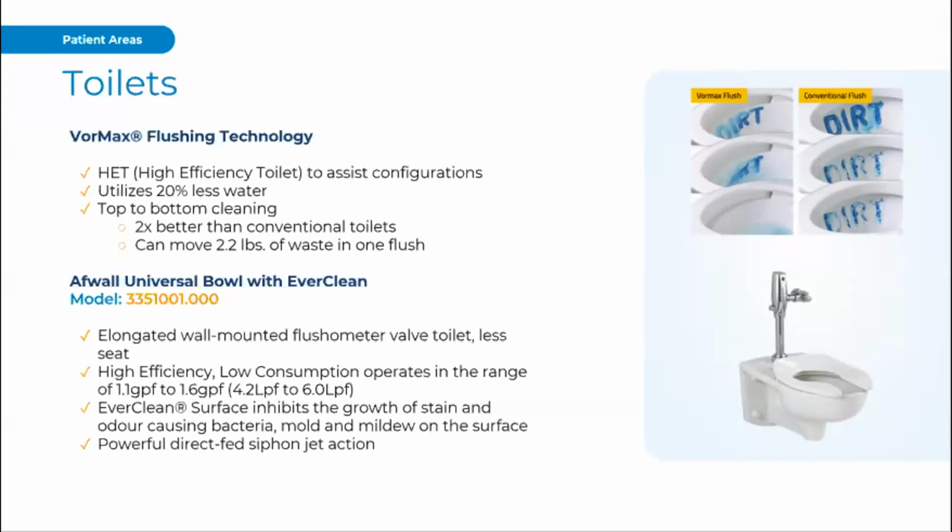Tank type will be quieter than a flush valve style, so that is one of the pieces that is commonly brought up. However, flush valve does come back up into the conversation because it will have a better line carry and an even more reliable flush than even the best tank type units. There's a lot of power in the flush valve style, which helps remove the debris reliably, and it does not rely upon the user to activate if we go with a sensor operated design.